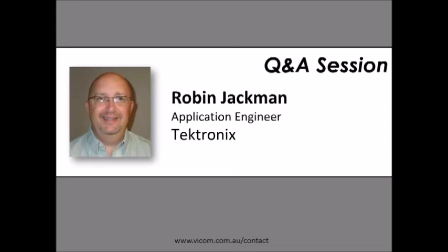As you reduce the reference level, what you're doing is adjusting the amplifiers and the attenuators in the front end of the instrument. And what we're doing is trying to get the maximum dynamic range possible. So usually my advice is lower the reference level until the peak on the display is as close to that reference level as possible. But at some point you're going to see an overload light come on, or an ADC saturation light, or a clipping light, or something like that. You want to back off your control a little bit from them.